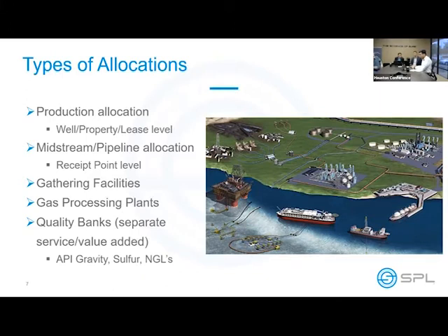Yes, sir? We have a question from Brandon. How about BTU allocation? Yes, Brandon, you're spot on there. And we're going to talk about that here in a little bit. What we've been talking about kind of implies that we're talking about volumetric allocations, but it's rarely based on just volume, if ever anymore. It's the quality of your product comes in there. So in the case of a gas, you're going to combine your volume with your heating value and get the actual energy, and you're going to allocate that out.